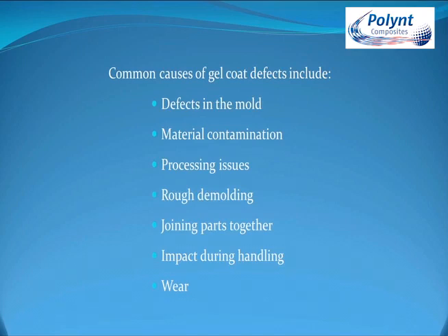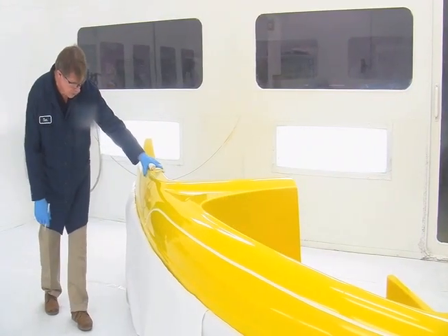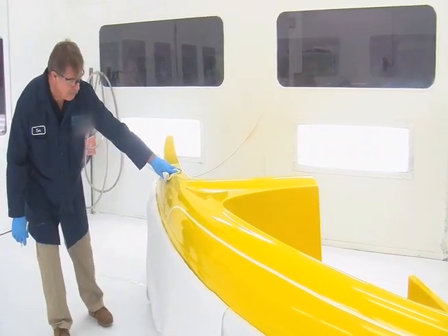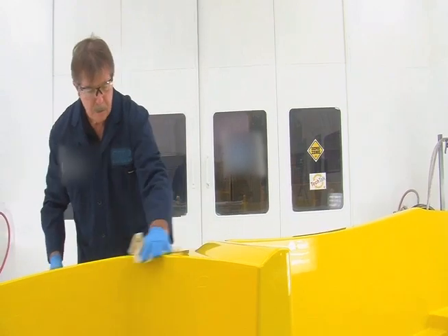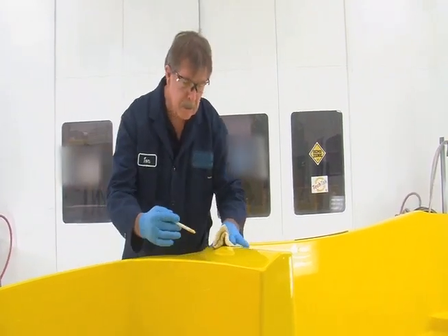If you suspect that the defect is caused by the mould, inspect the mould and consider repairing it. It may be more economical to repair the mould than constantly repairing parts. To determine if a repair is needed, stand a reasonable distance away from the part. For example, 3 feet is reasonable for a boat. If you can't see the defect, repair may not be needed.